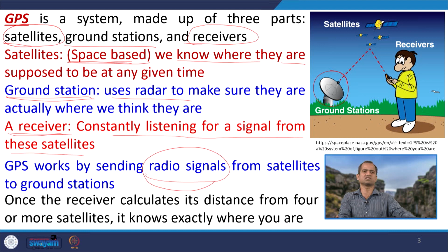Earlier we used back bearings, that means from 3 different places we draw the back bearing and finally locate ourselves at the intersection. The same technology applies here: if 3 or more satellites are merging their points, they are precisely locating me. How precisely they can locate me depends upon this intersection.